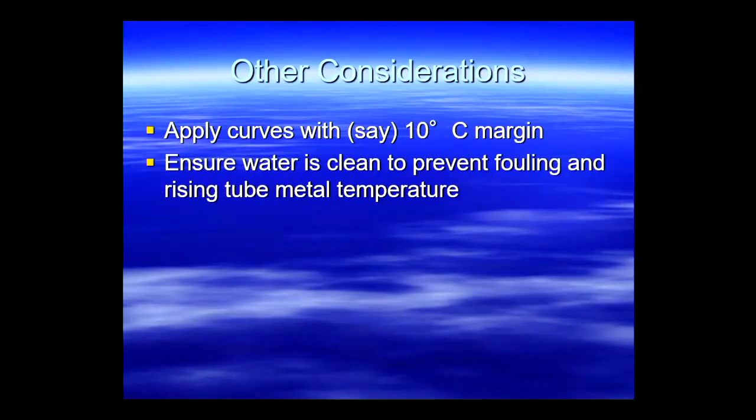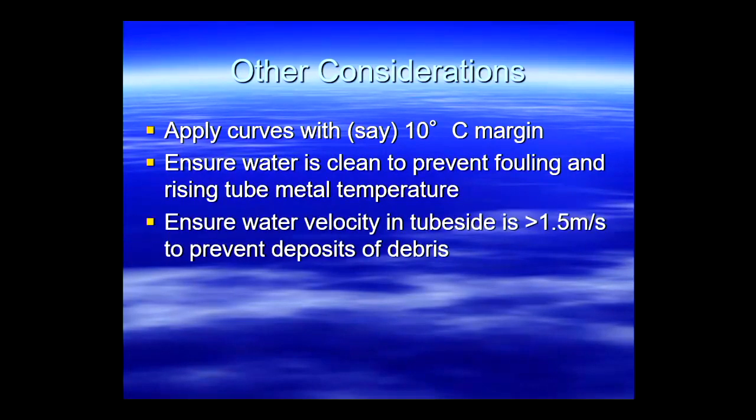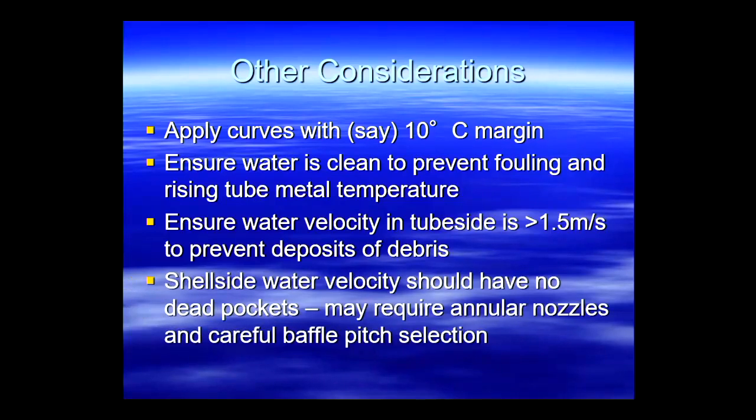All right, and there's various ways to use these curves, but I'll tell you a story about them first. One of the problems you have to deal with is stopping too much fouling. If you don't put biocide in, you end up coating all the insides of tubes with some sort of slime from all these bugs growing in it, you know, algae and so forth. So you've got to keep the water velocity up, and you've got to keep all the bugs well and truly dead. You've got to make sure there aren't any dead pockets for things to accumulate in and so forth. It's all part of the cooling water design.